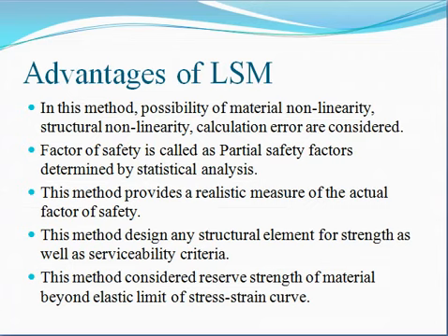And last is that this method considers reserve strength of material beyond the elastic limit of the stress-strain curve. See, when the material is loaded, first of all it gives elastic behavior within the curve. Means, what is that elastic limit? When the load is removed, the material gets its original size and shape.